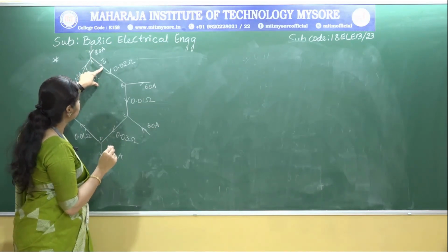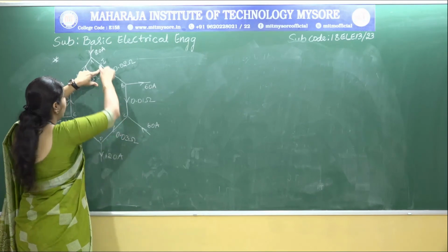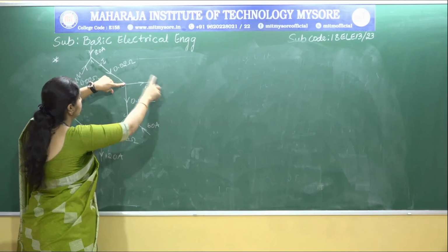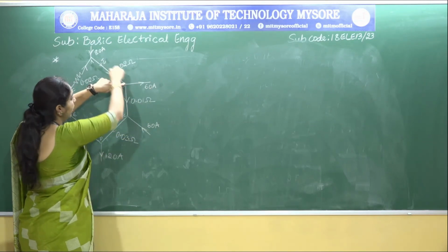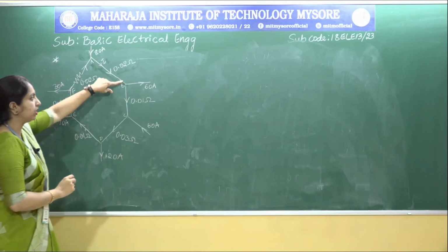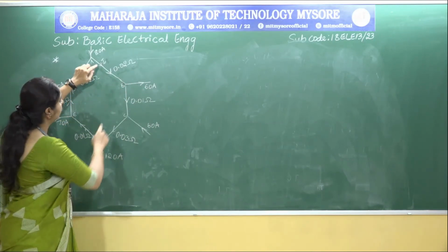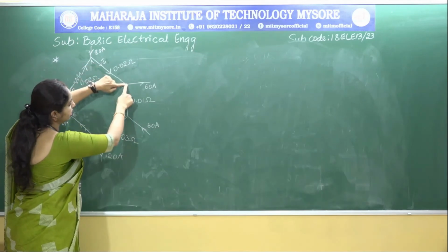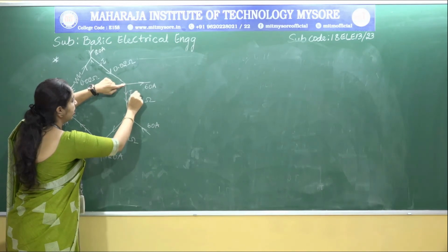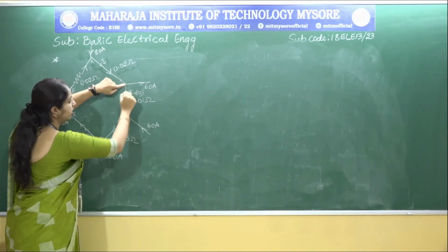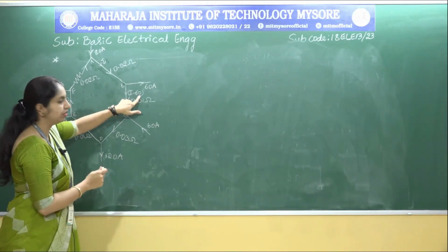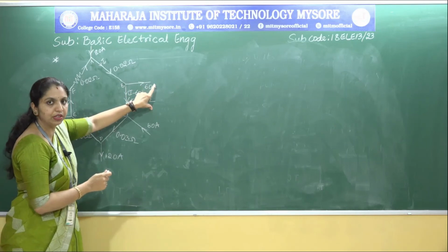Consider this as the total current I. Current I is entering this junction and 60 ampere is leaving the junction. So now look at the circuit carefully. When I current is entering the junction and 60 amperes is leaving the junction, the current here is I minus 60. Remember, the current passing through 0.01 ohm is I minus 60, because 60 ampere is leaving the junction.